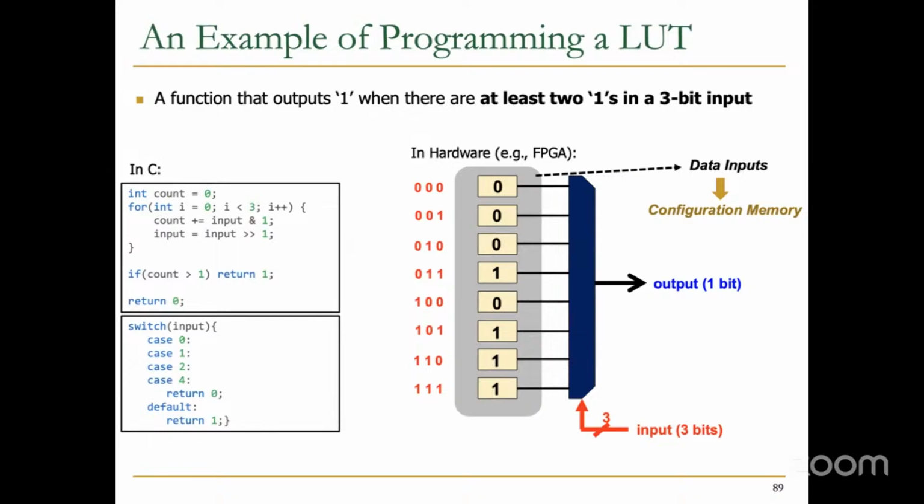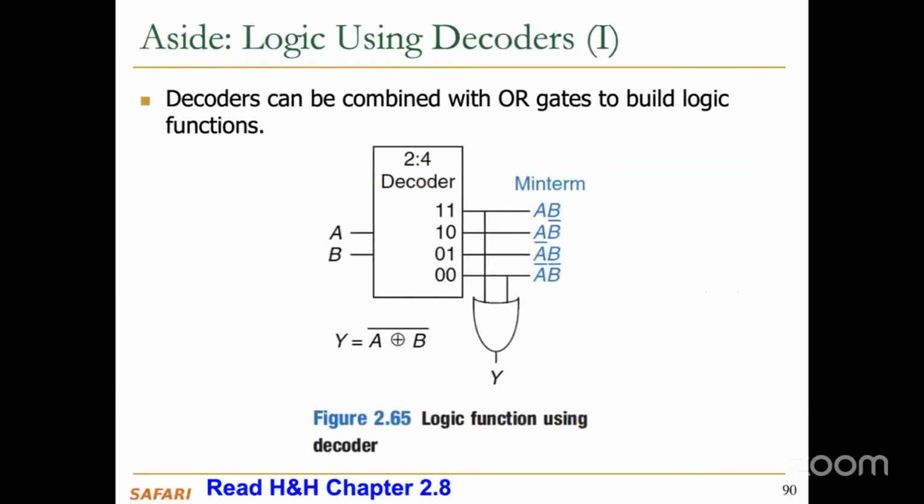for that. You can actually have a lookup table that has 2 to the 8 inputs, and you apply 2 of the 4-bit numbers as a select input to that lookup table. Make sense? This way, you don't need to build a multiplier. You do multiplication using a lookup table. Okay? So FPGAs operate using these principles, and you're going to program these FPGAs. That's why I cover this, because it's really interesting and important.